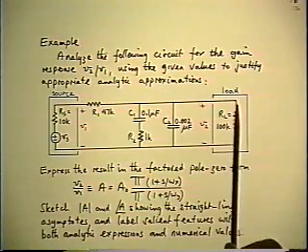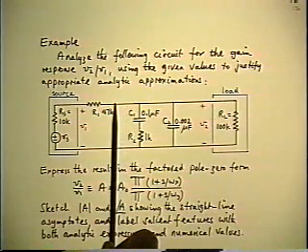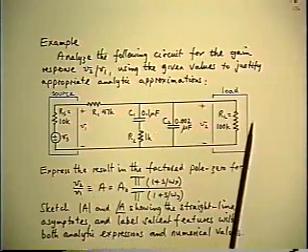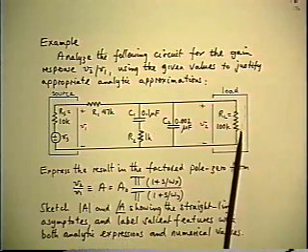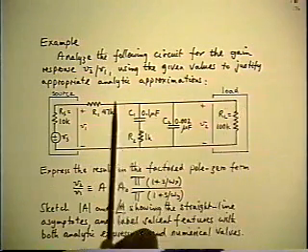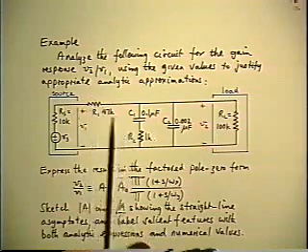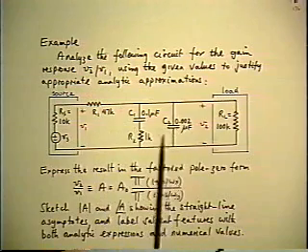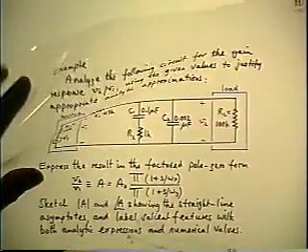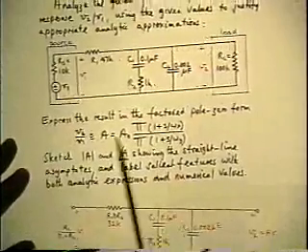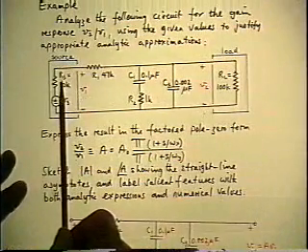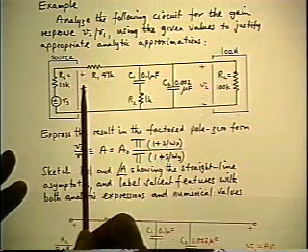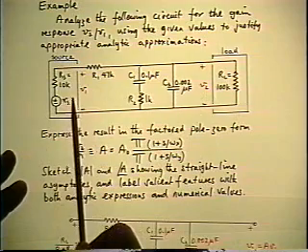This resistor RL could just as well be on the left of the other two branches. It wouldn't change anything, except it's a little more obscure to recognize it when it's out here. But if you simply move the RL to the other side, R1 and RL can immediately be absorbed into a Thevenin equivalent, and you're left with only two parallel branches instead of three. Incidentally, the RS is a red herring. RS has nothing to do with the result for V2 over V1. That wipes out a few of them right away, of course.